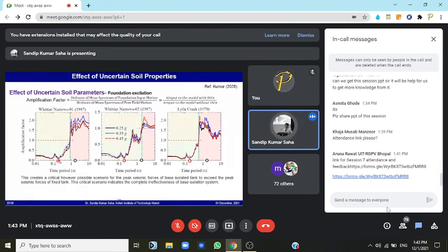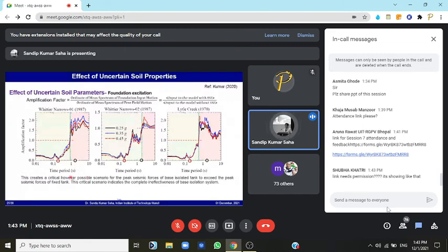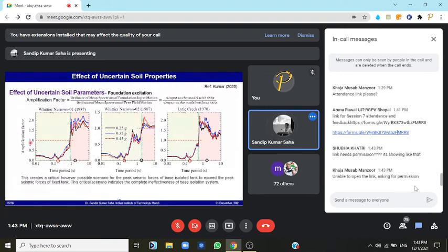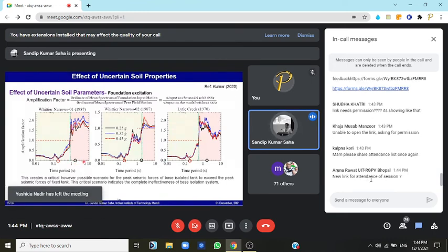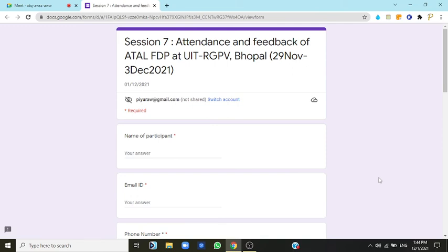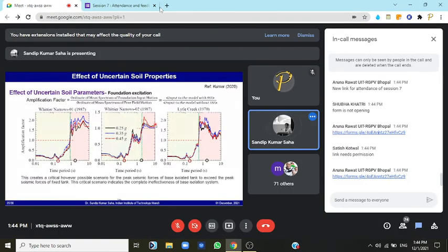observed like this. Here you can see the impulsive and the sloshing or the isolation frequencies plotted. You can see that for some of the earthquakes, considering the different levels, the amplification is quite high. It is going more than one when it comes to the isolation period. So whenever isolation is there, there is a chance that it may amplify the responses. That is the reason that for some of the earthquakes it is coming close to one, and for some of the earthquakes it is coming significantly higher than one.